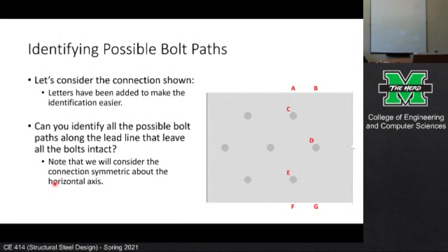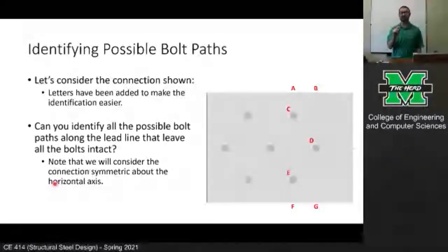Mr. Randall asks, is a fracture critical member just any tension member? Oh, you're throwing out some bridge terms there. All right, so fracture critical. I can talk about fracture critical all day long. The term fracture critical is a dirty word of bridge engineers, I guess you could say. But basically, and I'm using my own language here, a fracture critical member is an element in tension in a bridge that is perceived to cause systemic level failure if it fails. It's not always systemic level failure, but it's perceived.